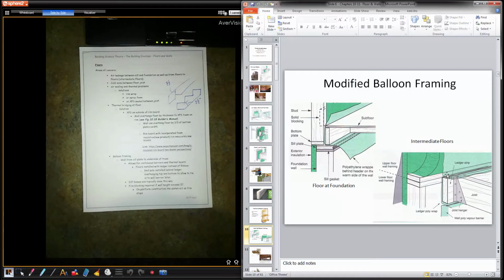So first you have to have plastic behind that ledger board. So a little bit above, a little bit below, to make sure you can tie into the 6mm poly on the upper floor, 6mm poly from the underfloor. That ledger gets nailed on, screwed on, lagged on, whatever the case, and then joist hangers for the joist to sit into. So what that's doing, as opposed to platform framing, we just looked at platform framing being very hard to insulate.